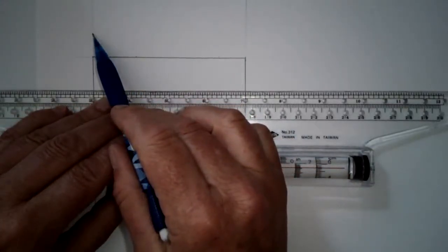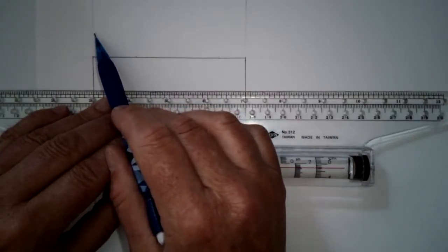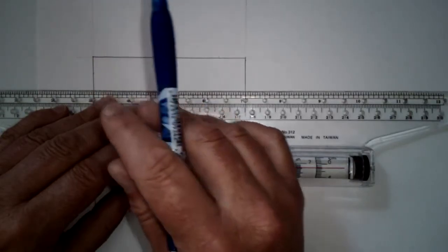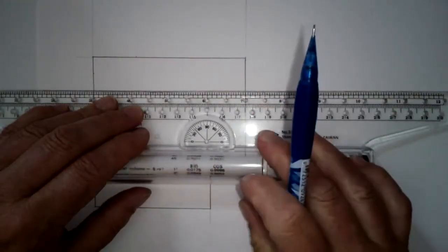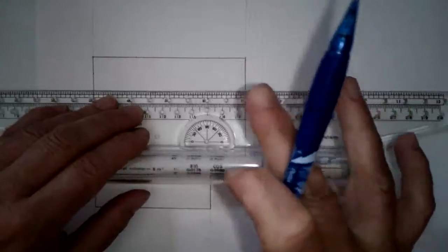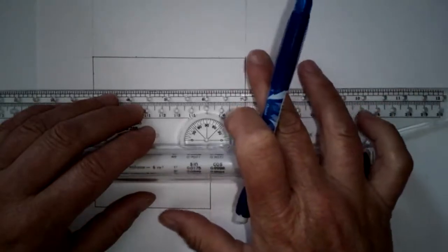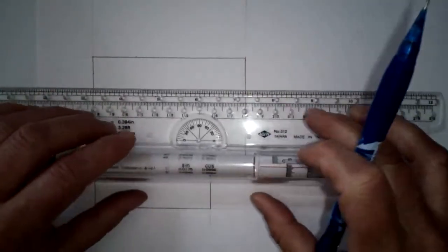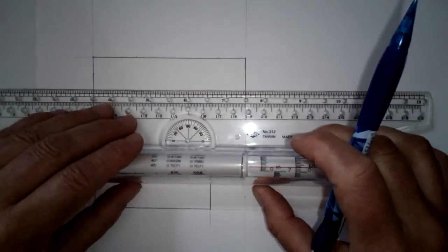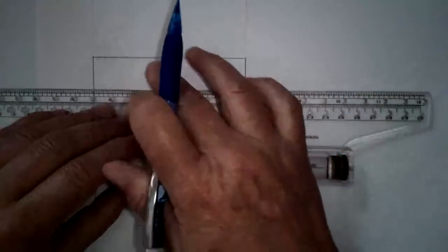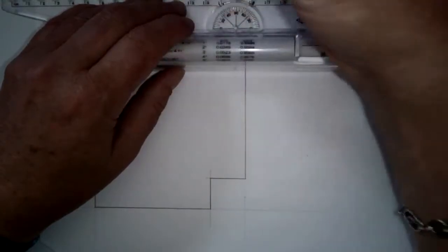This is a light line and it happens to also be thin. Light means it's barely visible to someone that isn't right on top of it. So if we were to look at this drawing from about arm's length away, we can't really see those construction lines. But I'm right on top of it. I'm the actual creator of this drawing. I want to be able to see those reference lines if I'm close to it. So a thin line is supposed to be dark still, but thin. It should be definitely different looking than the object lines. So I'm going to show the technique up here. Here's a thick line.